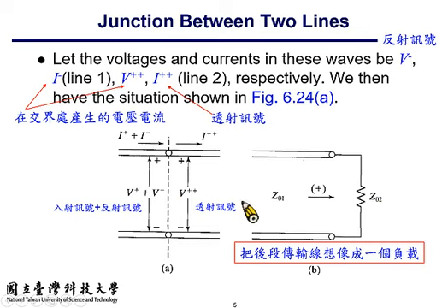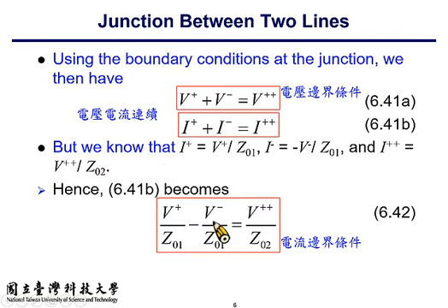The reflection produced at the interface is the same as the one produced by the termination. So it's okay to use a load of the same characteristic impedance to represent the follow-up transmission line circuit.